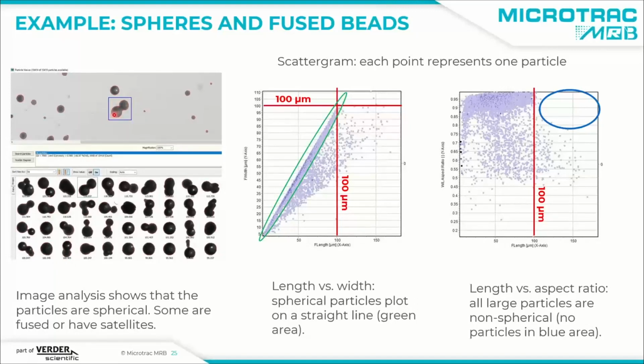If it gets signal from the length of the particle, it will think it's a big sphere. But in reality, it's just an elongated particle. And when you do the sieving, this particle will squeeze through a 100 micrometer hole, because sieving is orienting the particle on the sieve, and then it will just squeeze itself through the sieve by width, not by length.